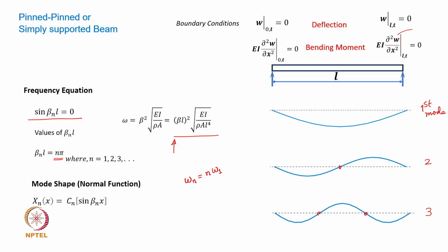And if you consider the beam cross section or a bar cross section to be varying with x, then the solution becomes quite challenging, and that is the reason why continuous systems are typically solved with those simplifying assumptions, and for complicated geometries or geometries which involve continuous change in the cross sectional dimensions, it's difficult to get the closed form solution for the natural frequencies.